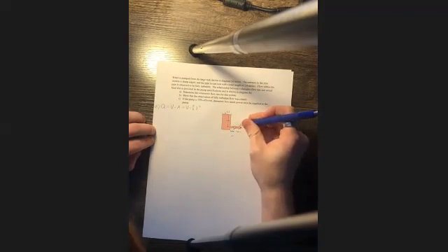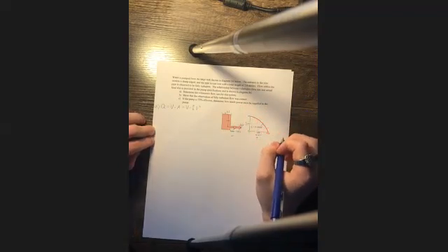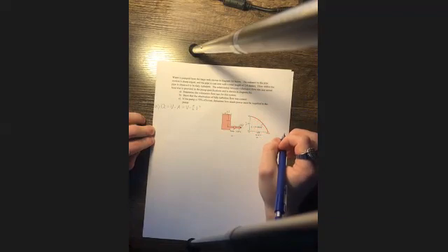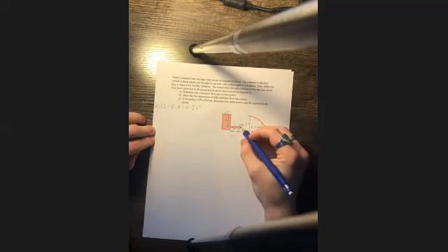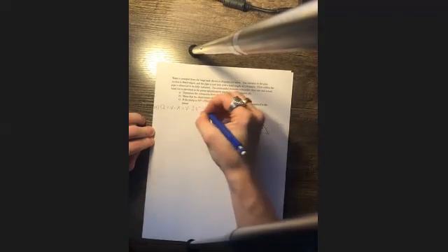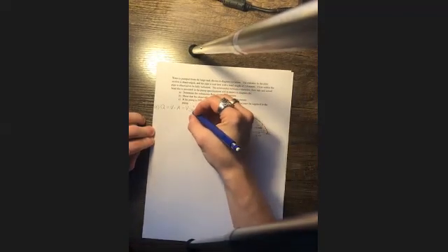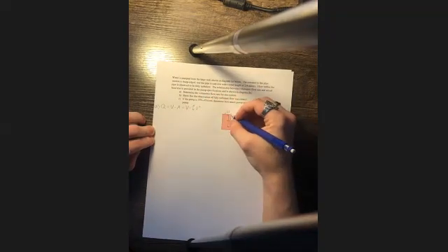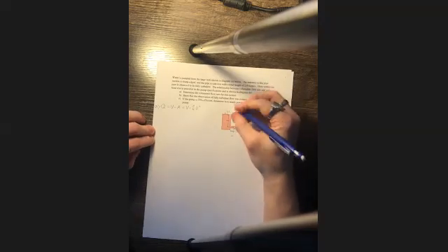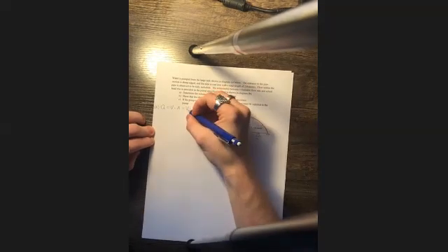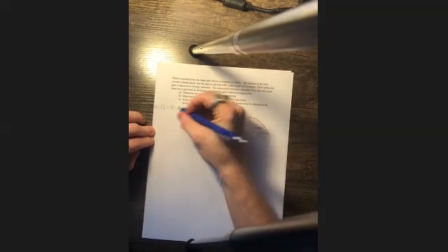Point 2 is at the exit of the pipe. The velocity at point 2 is the velocity we're looking for because it has the diameter, and velocity up here is really going to be 0 because with a large container, when it drains, the relative velocity of the top is going to be close to 0. So this is V subscript 2.